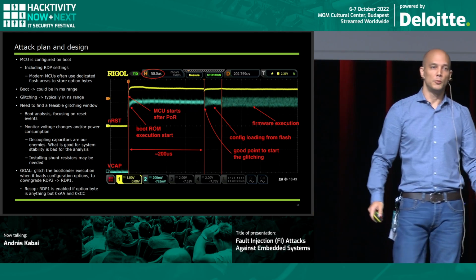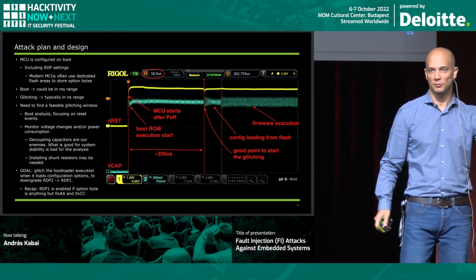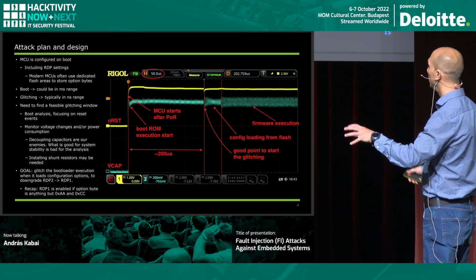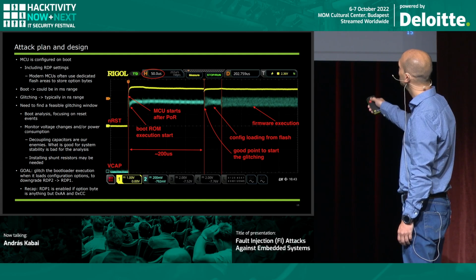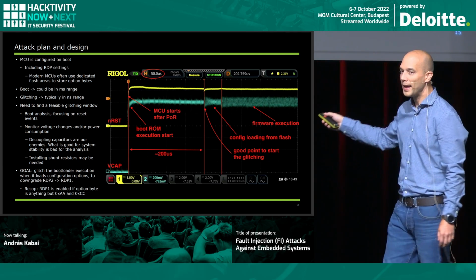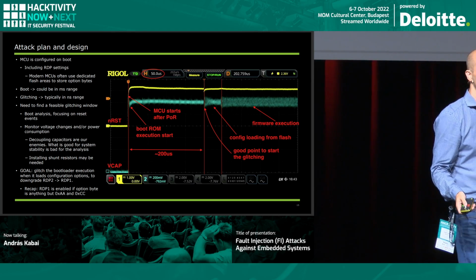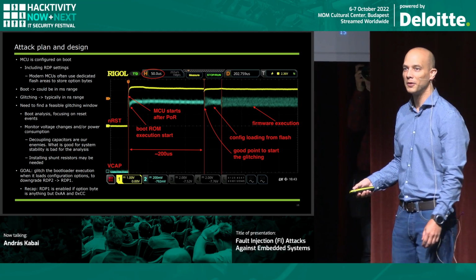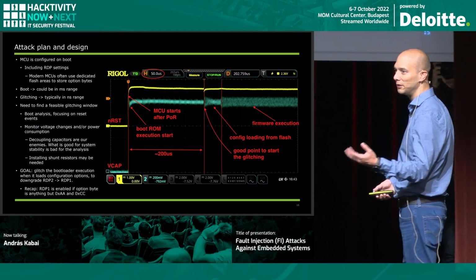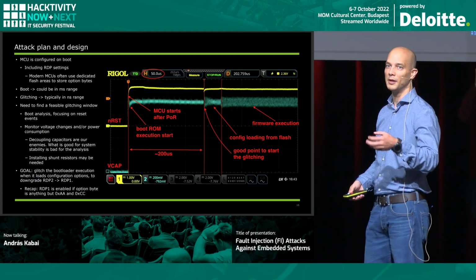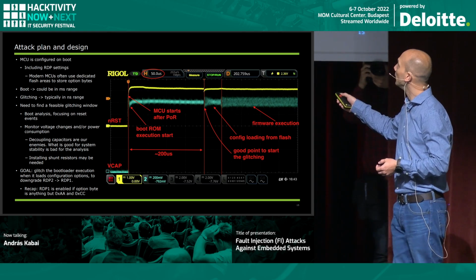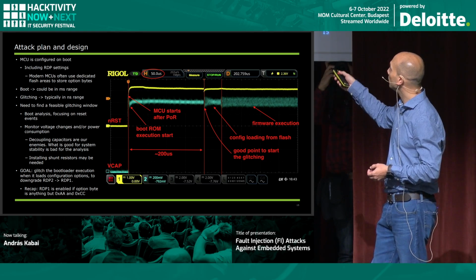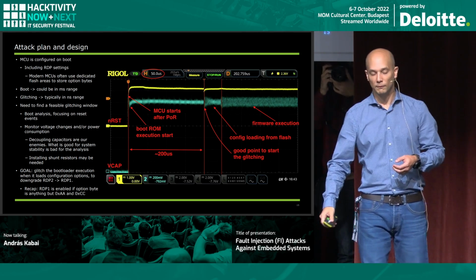Basically, there is a boot ROM burned into the microcontroller, so it starts to execute the boot ROM first, and after that, it reaches a point here where it will start to access the flash and load content from the flash. Because accessing and reading out information in the flash consumes more power, this is why you see different voltages and bigger fluctuation on the voltage line.